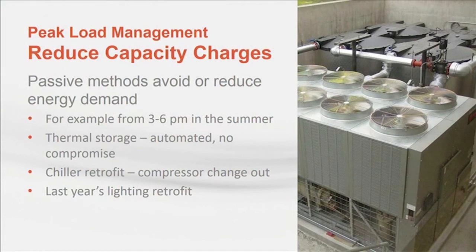As a result, you could expect to pay less for electricity supply in the future. As a more dramatic example, you could have a thermal storage system connected to your chiller, which reduces your summer afternoon demand all days. As a result of this system, you could expect to pay significantly reduced electricity supply costs because you have mitigated the grid operator cost component.